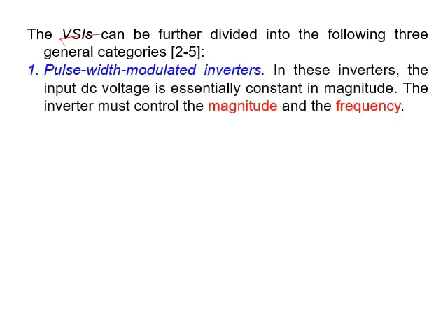In this circuit we could connect a capacitor between the AC and DC parts, so we call it a voltage source inverter, VSI, or we can connect an inductance link between them, a DC link, which is now called a current source inverter. There is not much difference between them, however they have different applications, but most of the circuits are voltage source inverters.